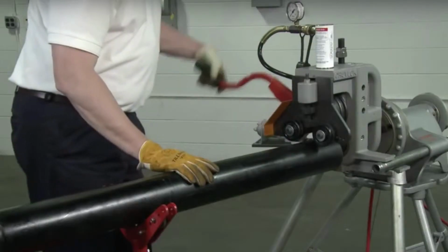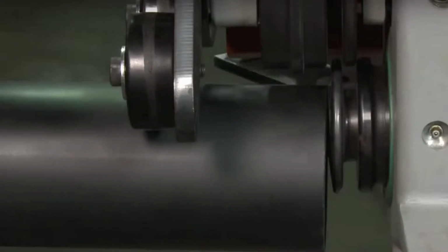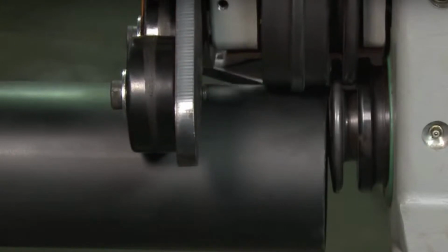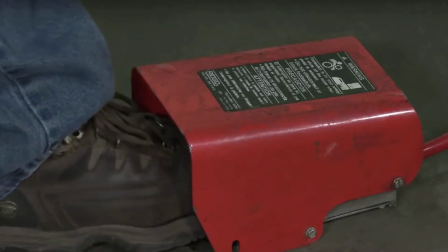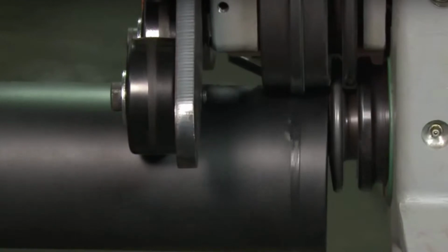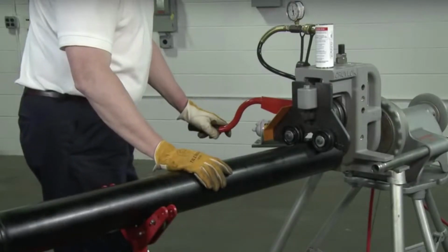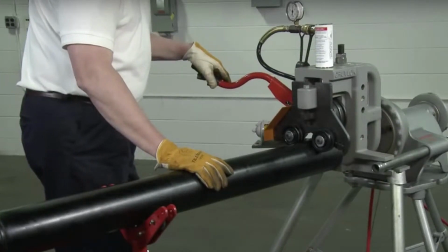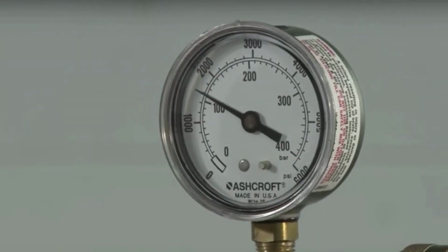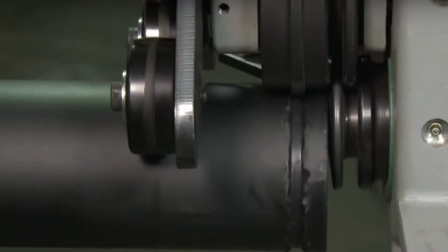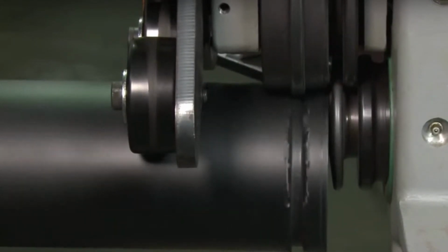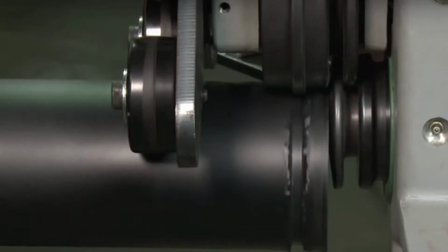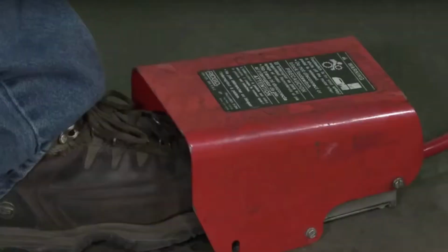Now, in the name of understanding pipe and installation applications, let's look at how a roll groove is made on steel pipe, and then I'll show you how a fitting connects. Essentially, steel pipe, Schedule 10 or Schedule 40 in most cases, is slid over a roll groover, which is connected to a rigid 300 power head. As you engage the roll, you add pressure and set the depth of the groove. You're hydraulically creating a rolled groove within that pipe.